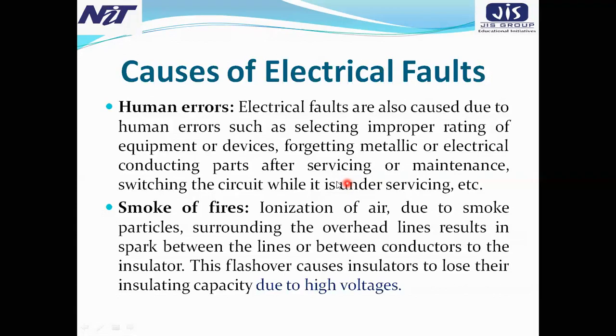So after discharging that current with the help of the earth stick, sometimes if the worker directly touches the cable, there is a chance for huge damage, because sometimes the charging current stays in the cable.